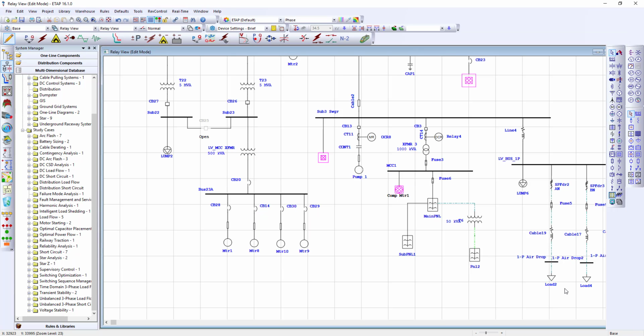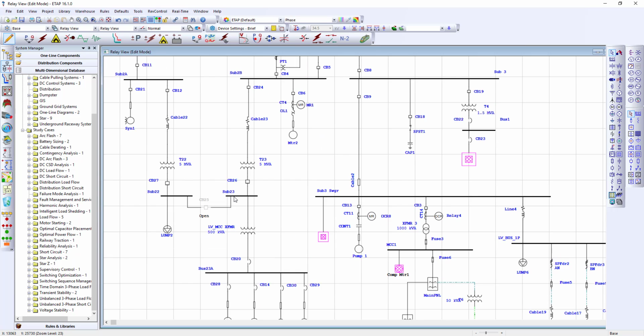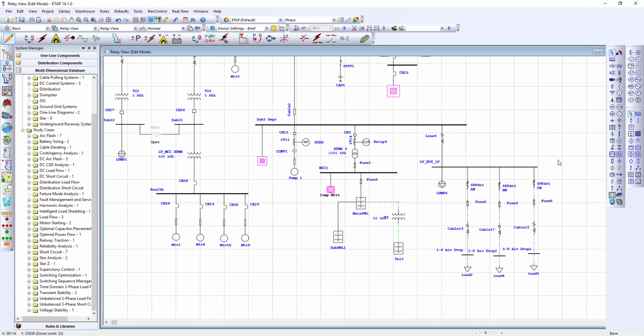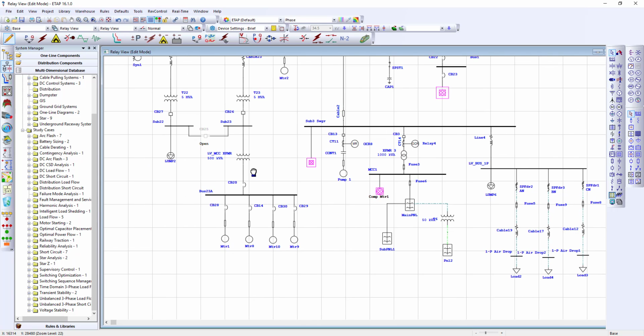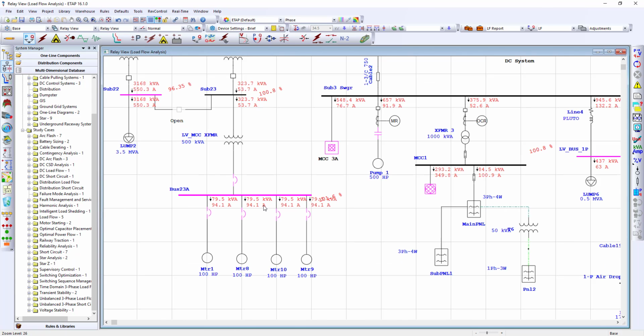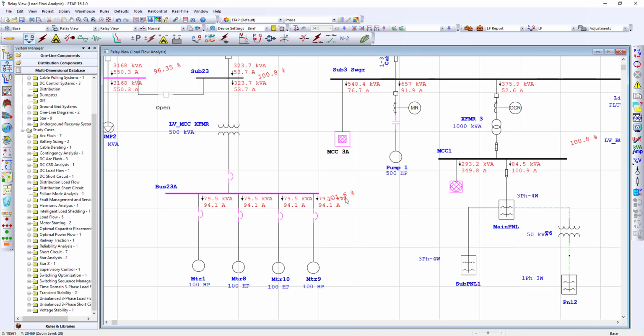And as you could see, it will automatically bring in all the changes. So this is the master project. It automatically brought in the changes for the expansion. Most importantly, it also keeps the changes to the single phase balance loading that we performed. So I'm getting ready here to perform a load flow analysis with all of the changes, and it seems everything checks out okay. Okay, this now becomes my new master project. So I just go ahead and click File, Save.